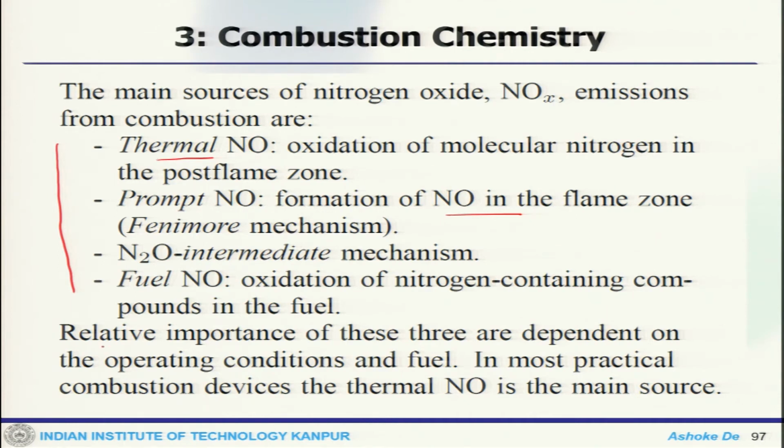As I mentioned, the importance of these is dependent on the operating conditions and the fuel. Depending on your operating condition, it determines which kind of NO formation would be there, or whether there would be no NO formation. But as I mentioned, in most devices you get to see thermal NO as the main source.